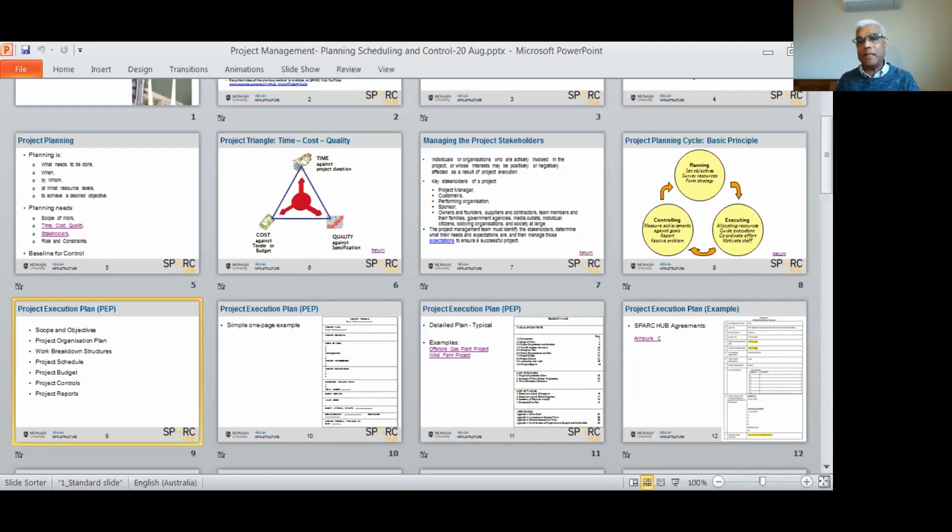We have a problem in our industry, the construction industry, when you have a work breakdown structure and the schedule in one way, and the bill of quantities in another way, then you have a problem. Of course, then your costing is based on the bill of quantity headings, whereas your scheduling is based on the work breakdown structures. So you need to incorporate these costing components of the bill of quantities into the work breakdown structure costing. So it's an implementation challenge.